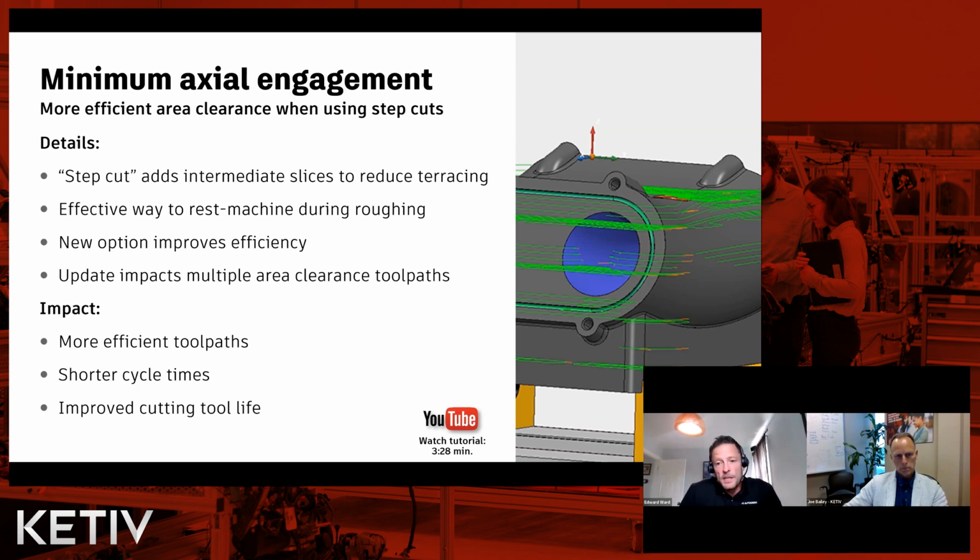So you'd introduce your step cutting, but the problem with that was you could end up with these small sliver cuts that would really be detrimental to the tool. First of all, it's going to be machining far longer than it needs to be. Plus, you run the risk of having to change your tool a bit more. It will do damage to the tips or the edges of that tool.